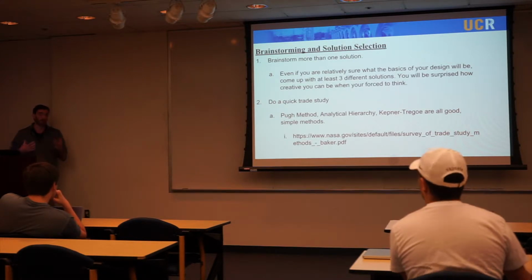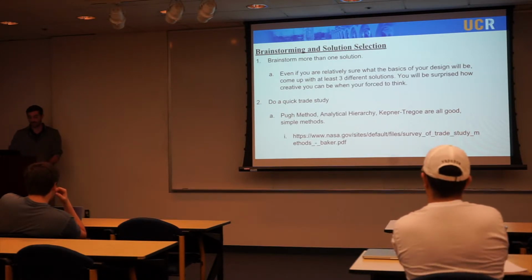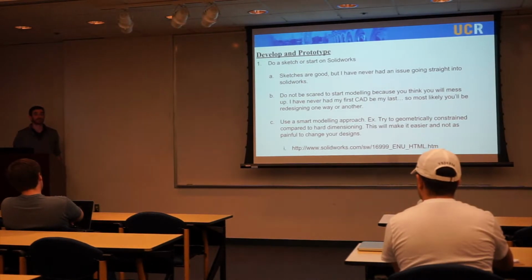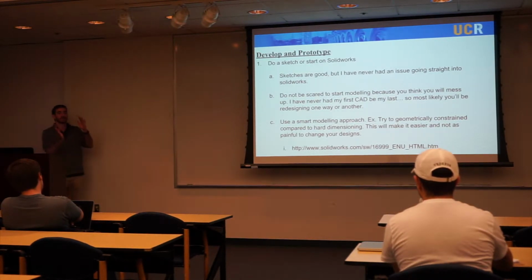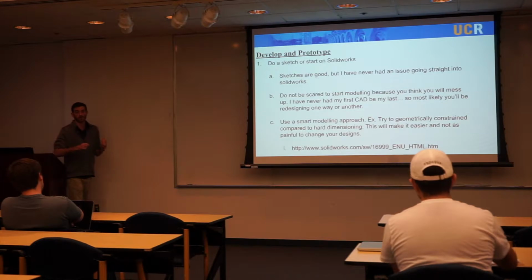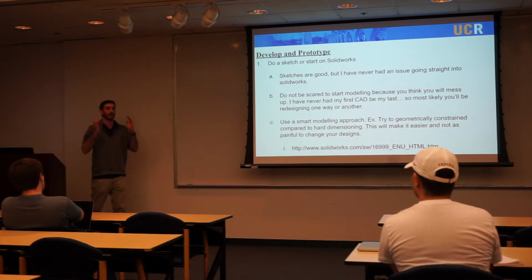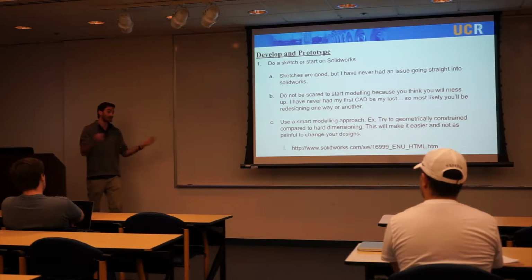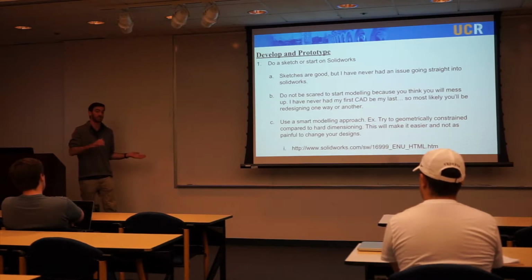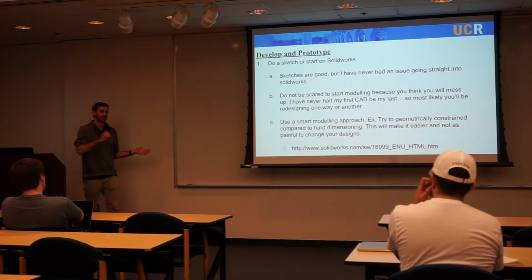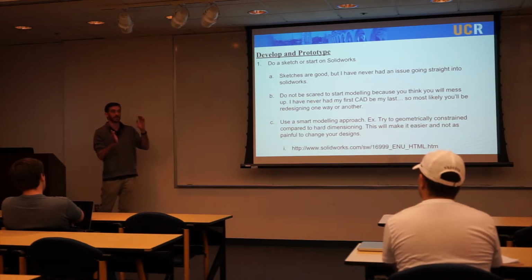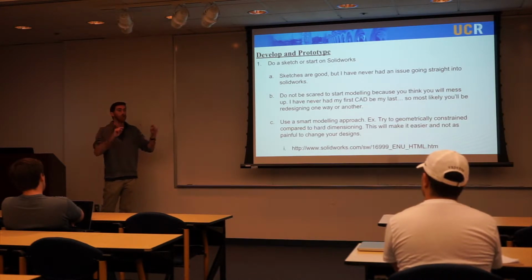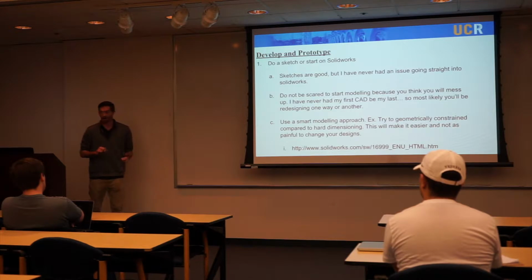But if you're all over the place, you don't know what to select, I've got try and use geometric constraints. Try and make things parallel. Try and use as little hard constraints as possible. Hard constraints being this segment is 3 inches. When you go back and do your redesigns, which you will do, you will thank yourself for having those geometric relations and just being able to change 1 or 2 hard constraints.